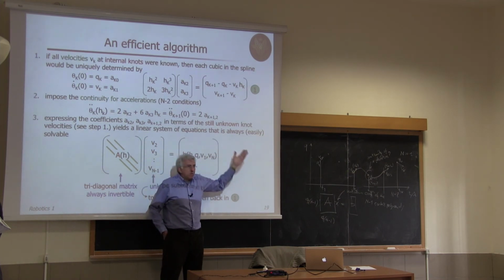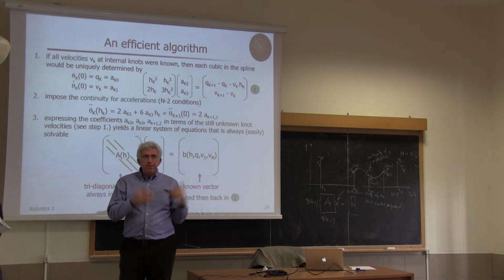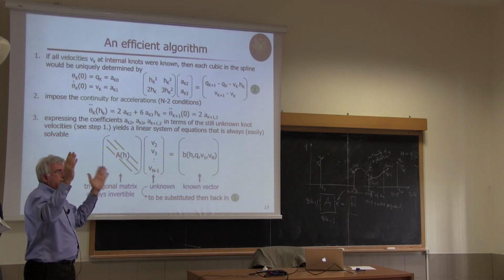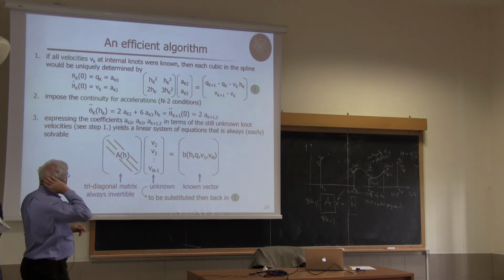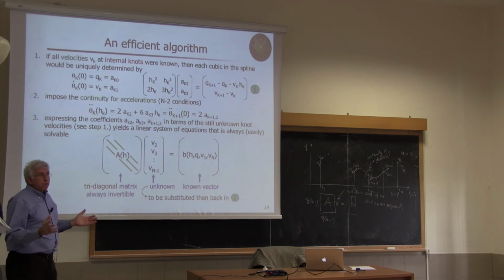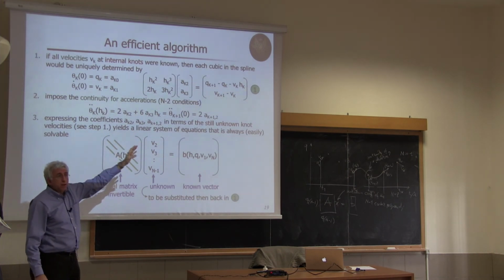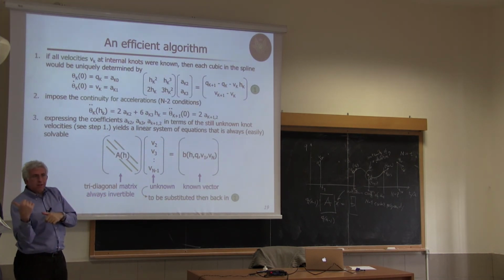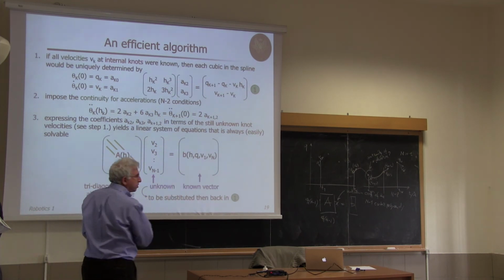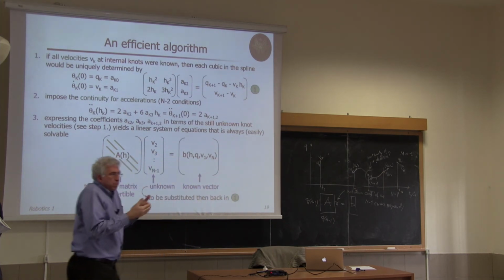And then you can solve this 2x2 analytically. Okay? So if I had Vk, Vk plus 1, as mentioned, this would give, as for a generic point-to-point motion, all the coefficients. Now, what is left to be imposed? Of course, if we repeat this for all intervals, the right velocity of the first interval and the left velocity of the following one will be the same.